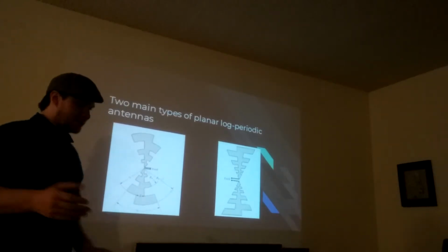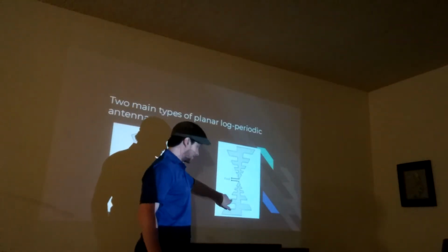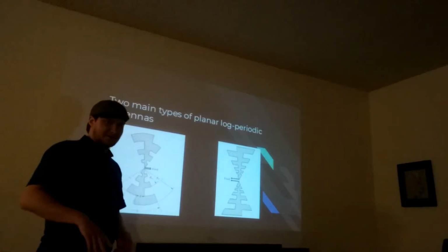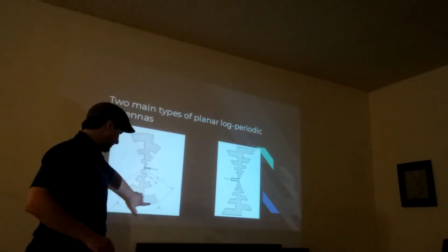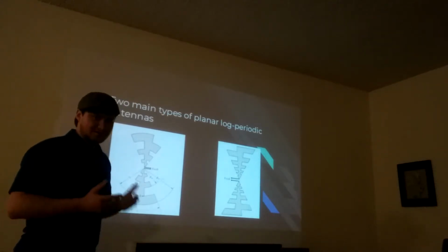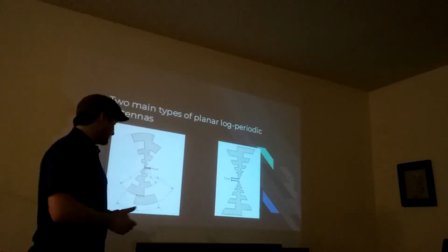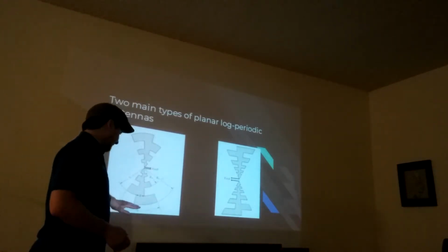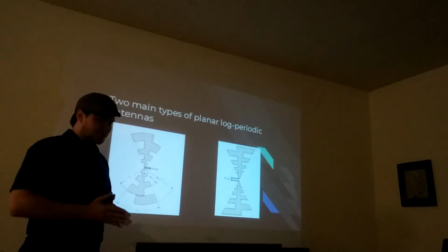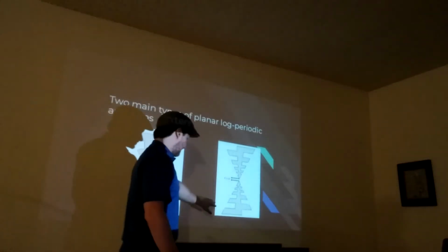Now, for the antenna that I chose, I did the trapezoidal toothed antenna because I only had a straight edge to work with. I didn't want to go through the hard work of doing a circular design, since I had already done the circular patch antenna, and I found that took a couple hours to get a nice curve to my circular patch. So I felt like the circular toothed antenna would be much more time intensive to build compared to the trapezoidal antenna.